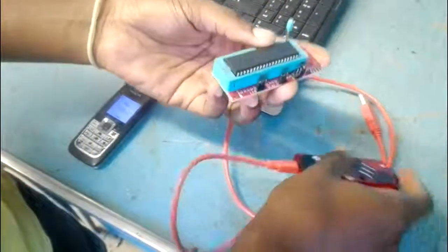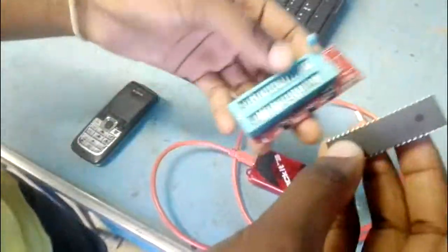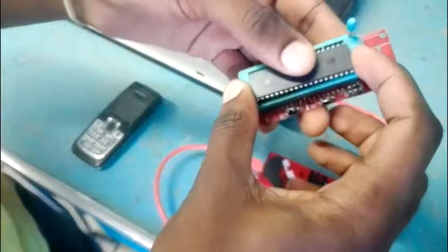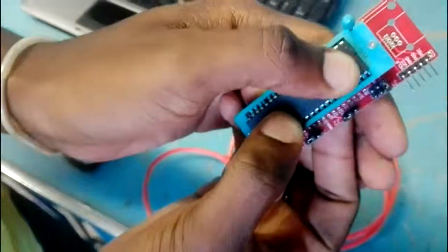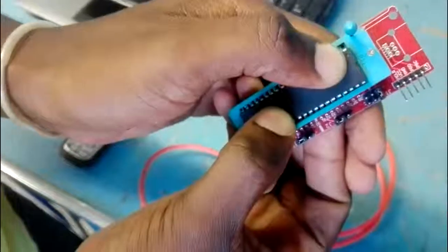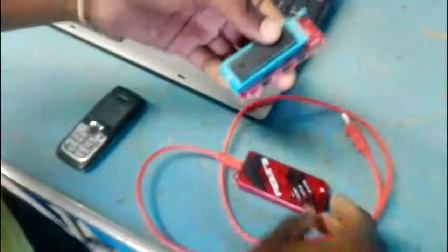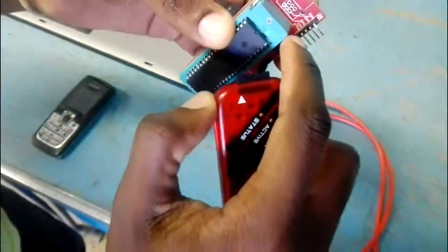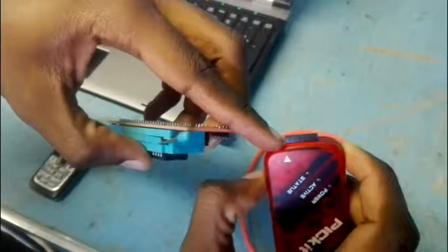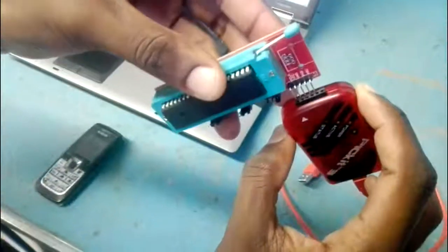Okay guys, so here I have my PICkit 3. You place your PIC on the tray here, and you make sure that the MCLR pin is right next to this lever. Then you pull it down to hold the pin down. Then the MCLR goes right next to the port which has this arrow. You place it right like this.